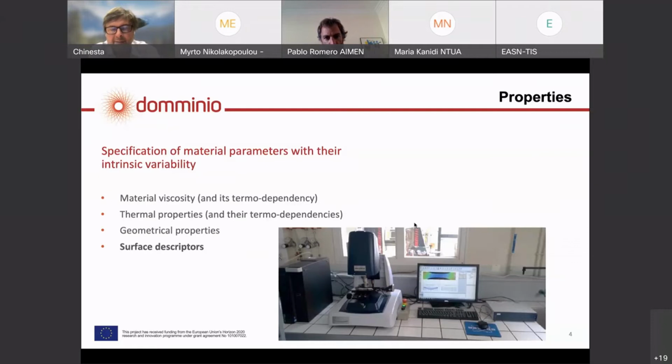There is something that is very important and is very difficult, that is how to describe a surface. Why? Because we have tapes, we have composite, prepregs, and the surface is not perfectly smooth. You have a rugged surface, and you have surfaces in the place in which you would like to ensure the consolidation. This means the diffusion of the molecules.